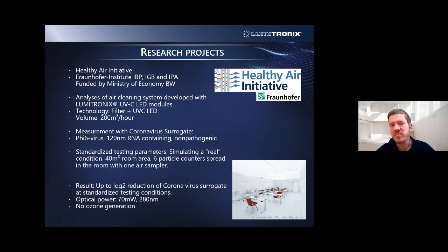The testing environment in this test pretty much simulates real conditions, with a 40 square meter room area. There are 6 particle counters spread in the room and 1 air sampler. It is not a testing condition with a very, very small area and a very, very small airflow. It is a tricky testing condition to get really good results.